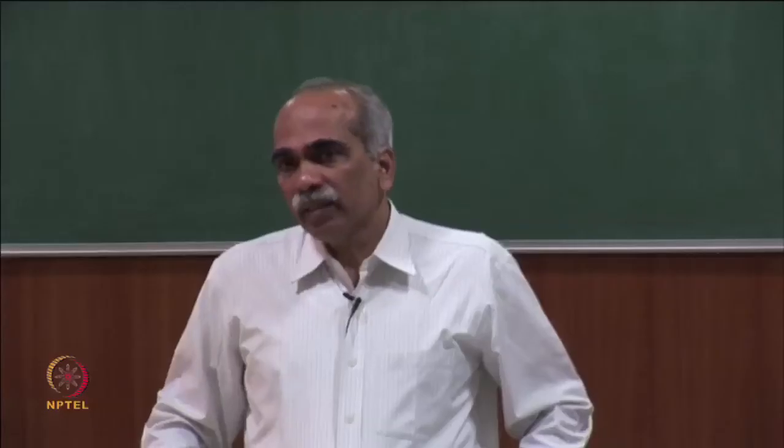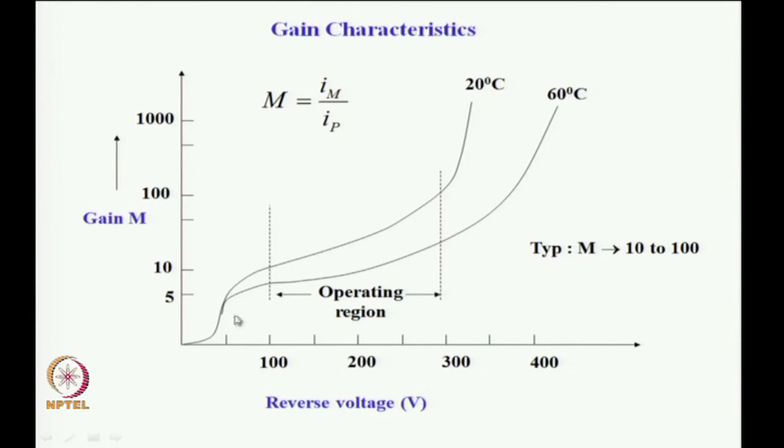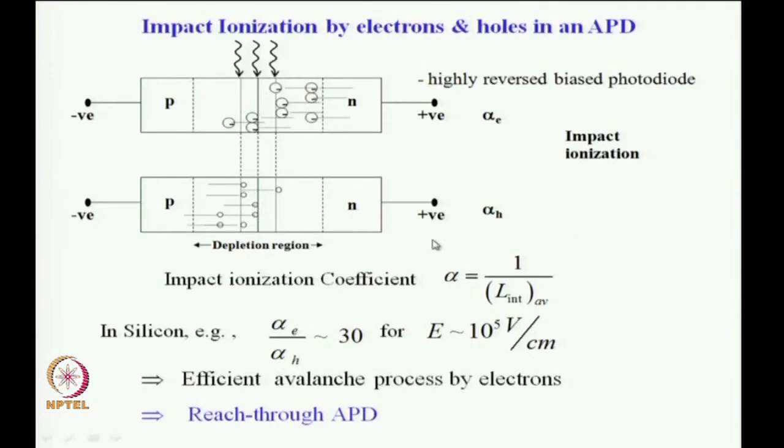At a different temperature, say a higher temperature, the characteristic varies. So, it is indeed temperature sensitive, and the characteristic changes because at a higher temperature we have more agitation of the atoms in the lattice, and therefore the electrons and holes undergo more collisions, that is, the separation between collisions, the average length. So, let me discuss in the next slide and then come back.